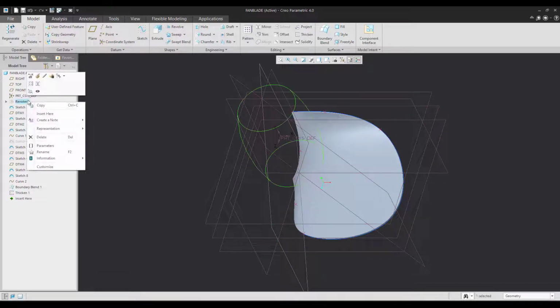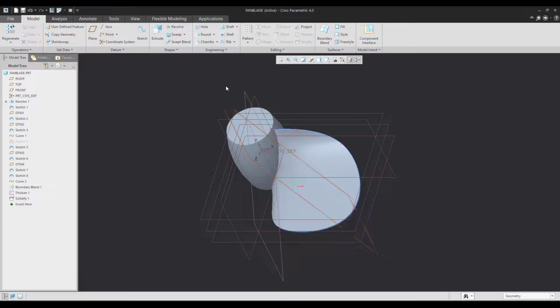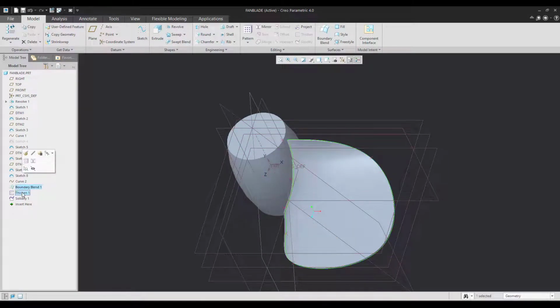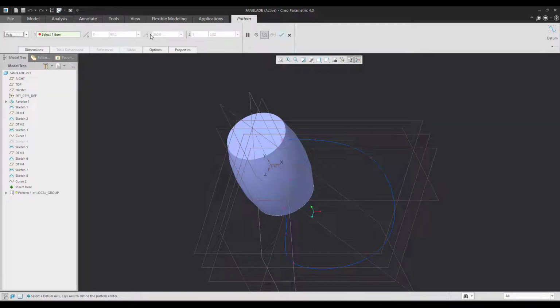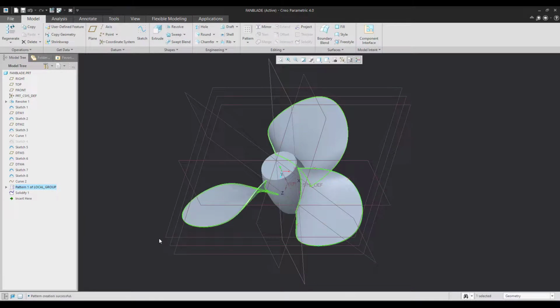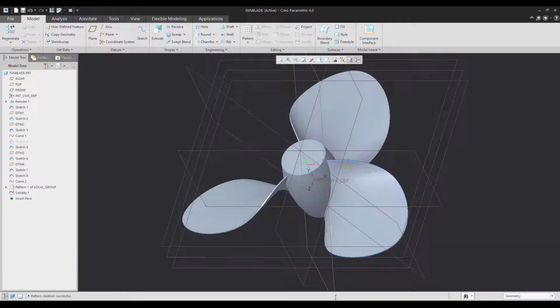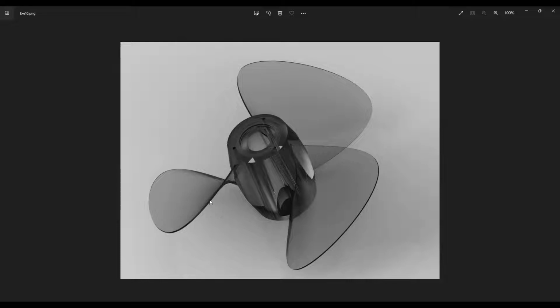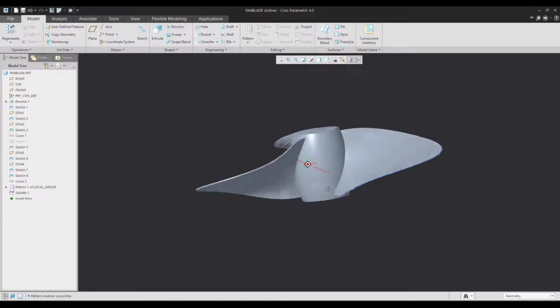Now, I would like to unhide the revolve and solidify the revolve. In a few conditions, you can do these separately. Now I can directly select the boundary blend and thicken, and then I can convert it into a group and pattern it, since there are 3 different plates in the picture. So I have an axis, then I require 3 for 360, then it takes 3 different plates. As you can see, it matches with the picture. You can see the first, the second as well as the third blade.